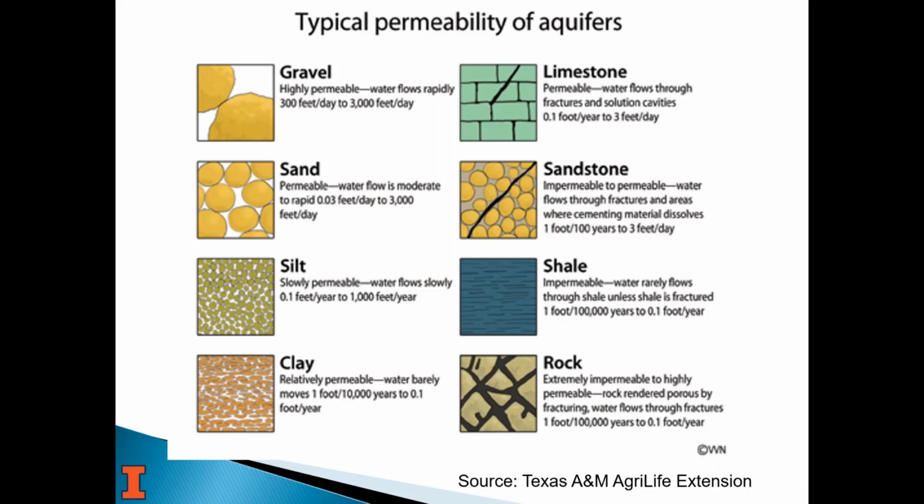And most of the time when we find clay or silt, it's a layer that's between sands and gravels, or sand and gravel, and then bedrock. I guess that's not right. It's above sands usually, but it's a clay layer that was deposited, and it puts a cap on the aquifer basically. And on the rock side, on the right here, there are a lot of different kinds of bedrock.